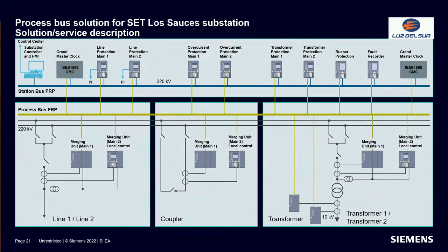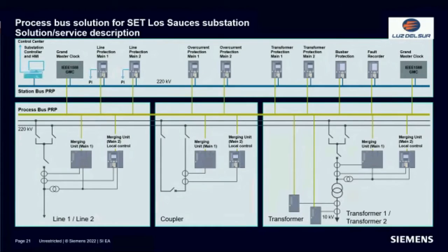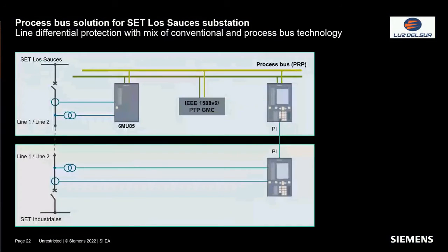One thing I want to mention is that if the protection relays need to send a command or a trip to, for example, a circuit breaker, this kind of information is sent via the process bus network. This is a complete digitalization of the substation. Please, next slide, Andreas.